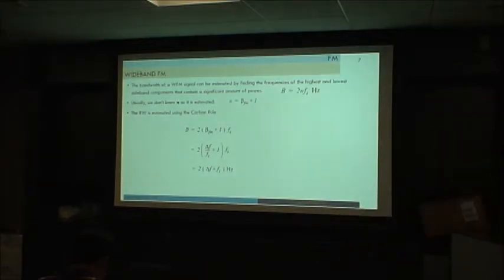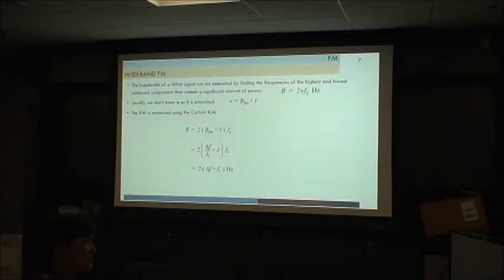So what's going to happen here? Maybe you don't remember, but for sure you should see this. Let's say the real spectrum is this guy, but what I am allowed to transmit is just this guy. So this is 200, and the real one is 256. So we are attenuating these high frequency signals. To solve that, I don't know if you remember, there was something called pre-emphasis and de-emphasis, which is to solve this situation.